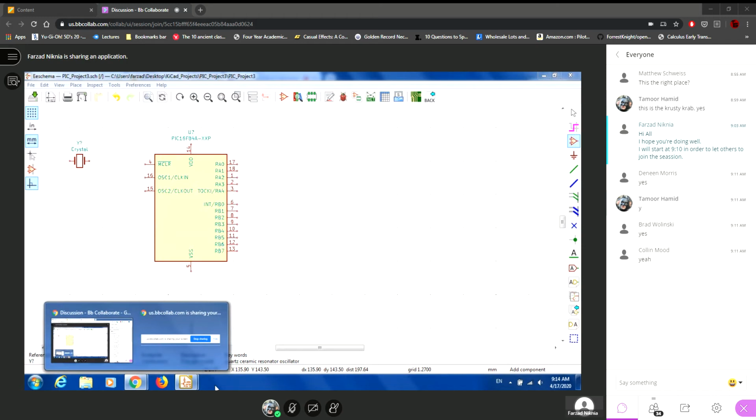And using just programming, you can set the clock of the microcontroller. But some of them don't contain any crystal, and you can use, for example, crystals with different clock cycles, like 8 megahertz, 16 megahertz, to generate a clock for your microcontroller.